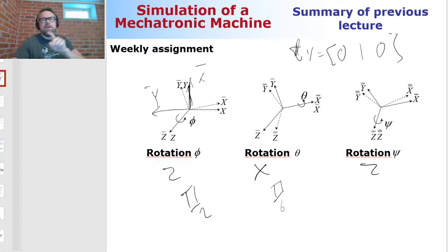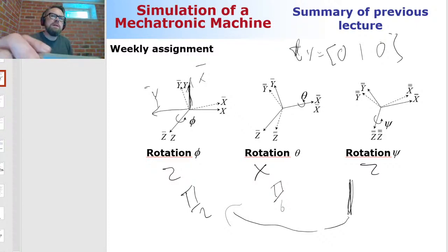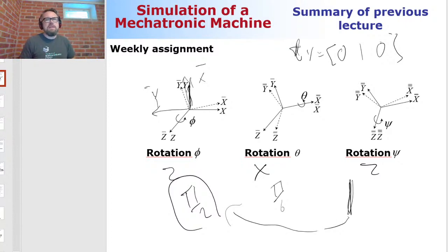So the only remaining task is that this last rotation has to compensate for the first rotation, because the first rotation was kind of an artificial rotation to put the x-axis in the direction of the y-axis. And we can compensate for it. The way we can compensate is to take the same amount but in the minus direction, so we can eliminate the first rotation. You got that concept? It's a little bit weird and it takes a little bit of time to play with your fingers to realize how it goes.